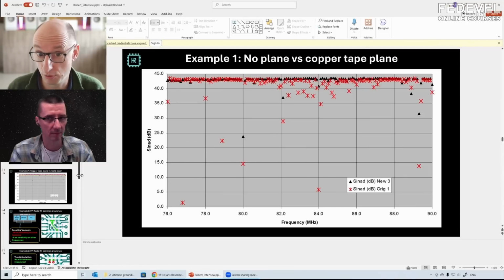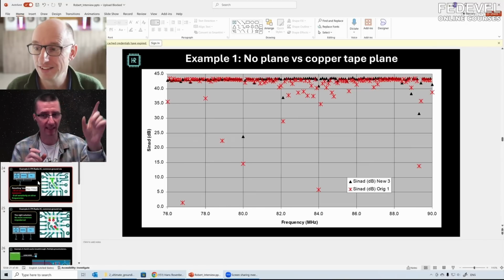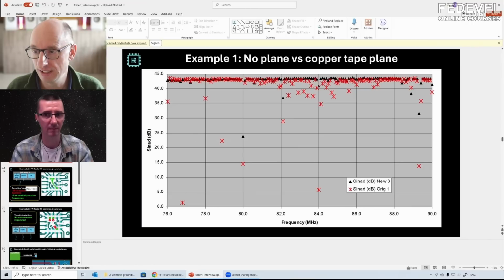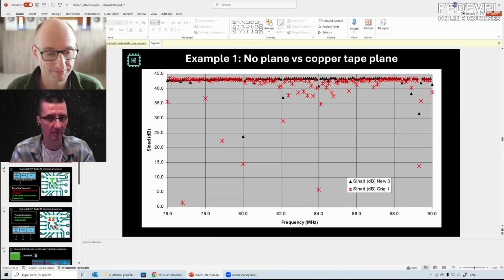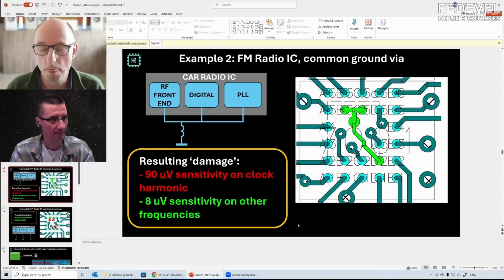All these antennas I talked about, you're creating all kinds of antennas everywhere, transmitting and receiving antennas, and they're doing their thing and basically ruining the performance. And the antennas are basically the pieces of tracks? Yeah, pieces of tracks. And the unwanted loops that you're creating. Because large loops, because there's no ground, so the loops will always be much larger than when you had a ground plane, basically.